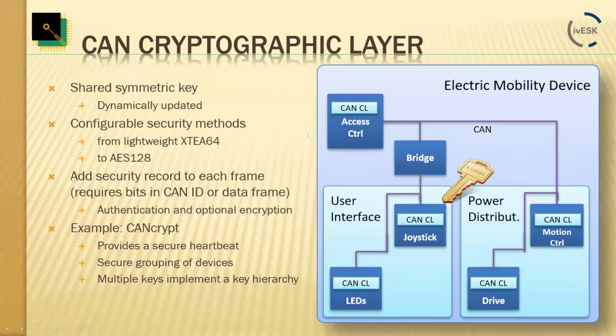Now, for the future CAN XL, some of you, I know from looking at the list here of participants, are well aware of CAN XL and the definitions there. I didn't specifically include it here because this is really not yet commonly available. However, security there is really handled directly. There will be quite a big additional data block added also to XL for the security, allowing really full-sized hash signatures to be transmitted. However, for both classic CAN and CAN-FD, this is really not an option.